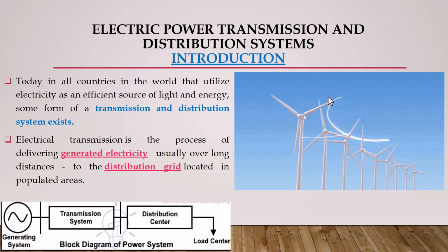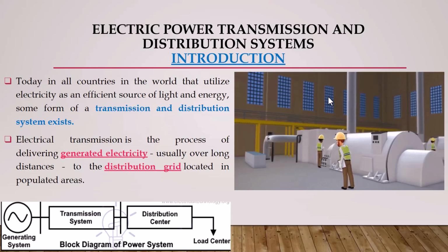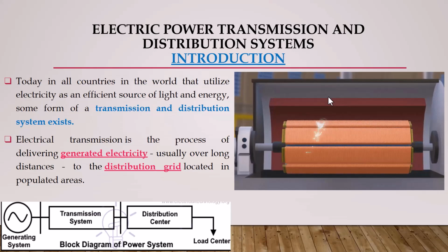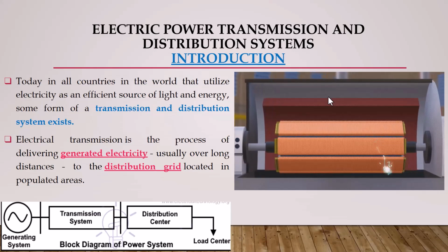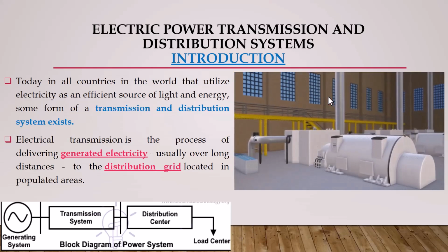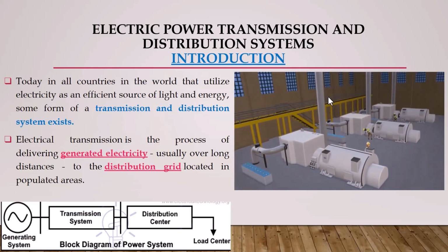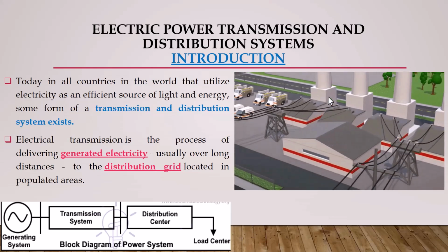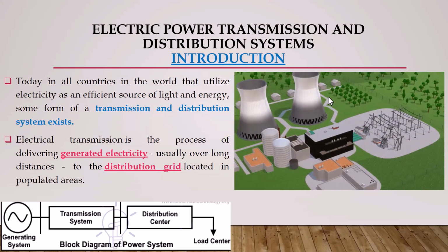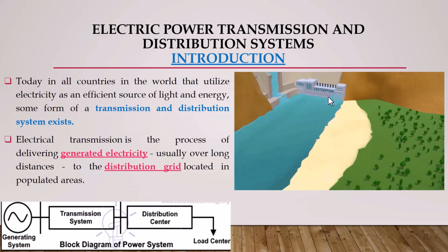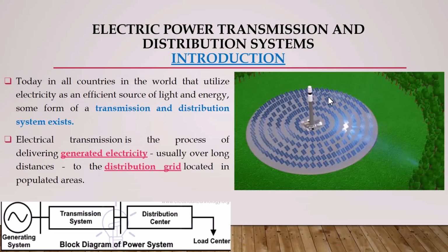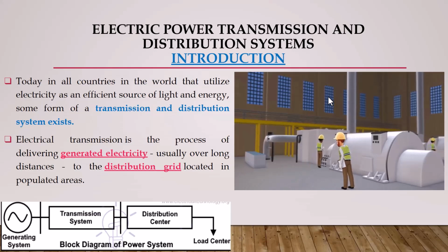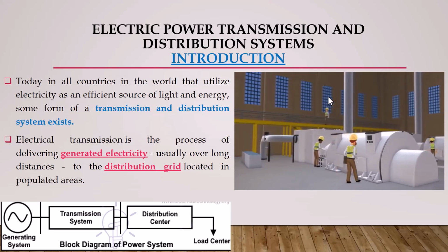This 11 kV power is then supplied to large commercial and industrial consumers such as factories, manufacturing plants, or large-scale commercial operations, which have high energy demands. These heavy consumers typically set up their own substations to receive, control, and utilize this high-voltage electricity efficiently. They receive it through a three-phase, three-wire overhead system that carries the 11 kV supply directly to their facilities.